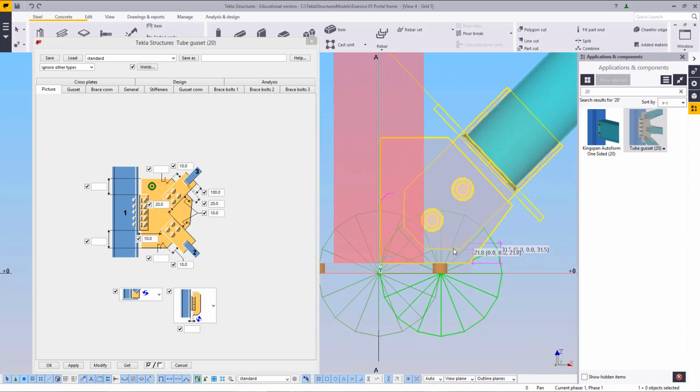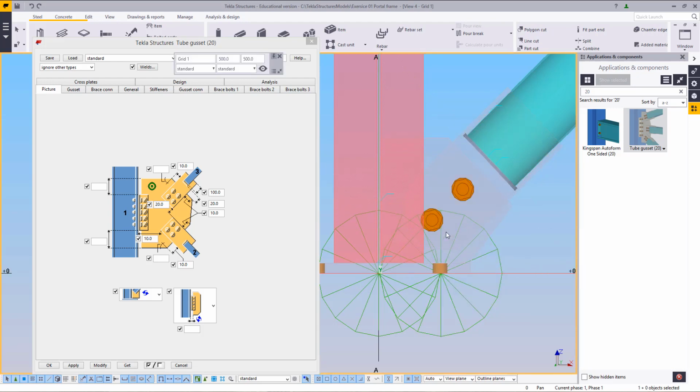Now, the reason that is not accurate, firstly, is because it's measuring its clearance from this side and not from the bottom side. So, because it's only using the one side, the amount that you use is not necessarily the amount that it is away from the steel or the closest clashing item. Secondly, it sees this as a square. In other words, whatever fictitious corner there would be over here, it's 10 from that, and not 10 from the cut corner that we're currently using.